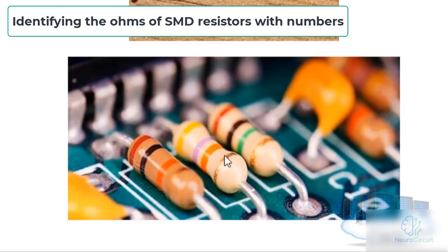Look, these resistors should all be roughly the same color. Well, but you can see that this resistor looks baked and dull in color. Of course, there are resistors that are colored by default, but how can you tell if it's burnt or if that's just its color? The first thing you should do is look at the resistors next to it, because usually in circuit board designs, resistors placed next to each other are within the same range and value.